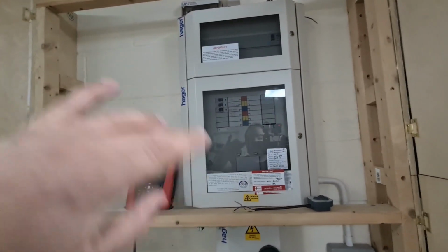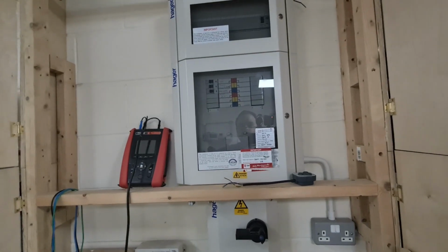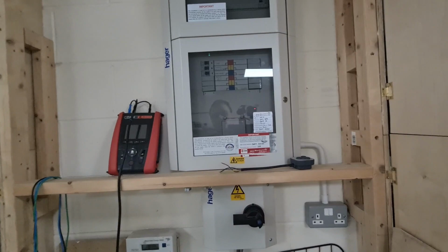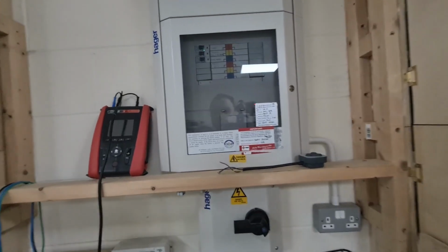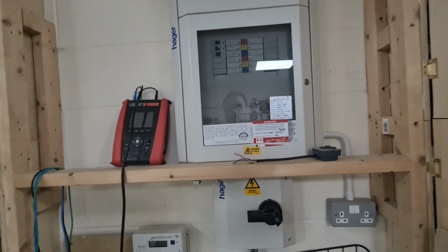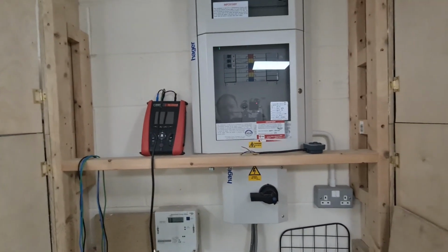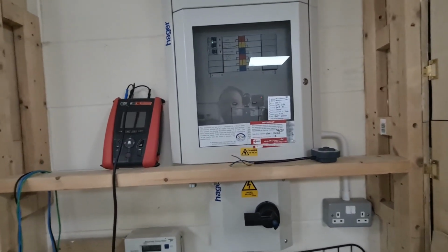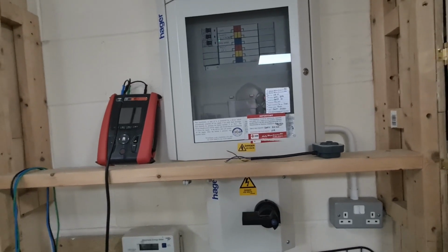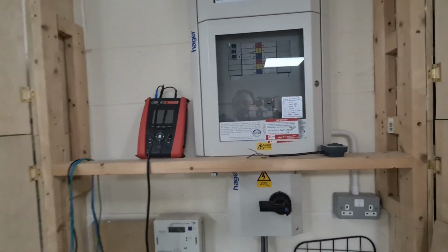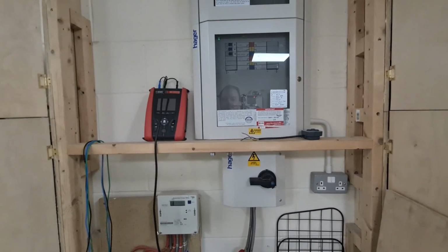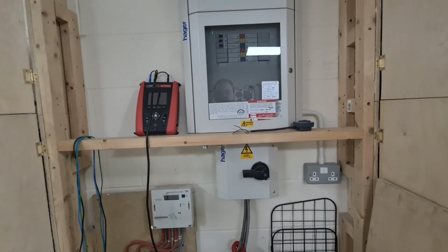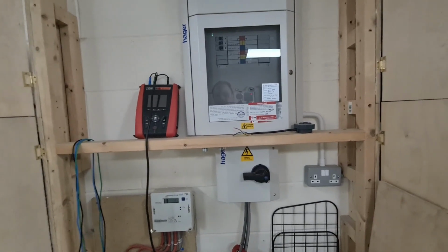We're going to have a look in here. I'm going to get all the power off, obviously, and we can go through the dead tests. I will obtain a measurement of ZE as well, because we're going to need that. And I will also show in the calculations how by inquiry we can use that figure as well, and how that affects things, and explain a little bit about the effects that can have on high power circuits with long distribution cabling when you're working with a small value of your maximum earth fault loop impedance, and how the calculation sometimes doesn't help you with that.